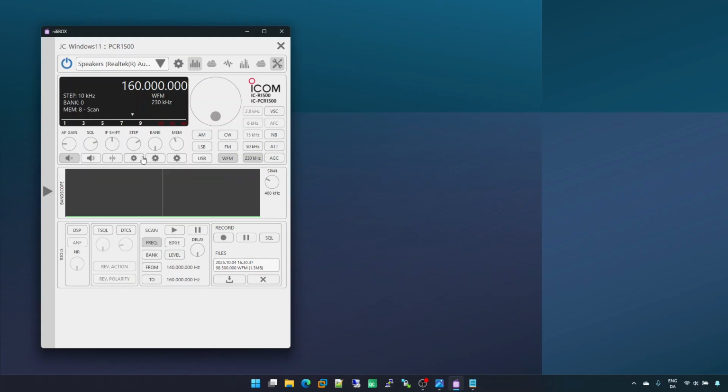Second step is to select what step you are going to use for this scanning, what is the squelch level that you want to use to consider that it has found a certain frequency, and what is the delay. That means what will be the speed, how fast the scan will be done. Now if I press on start, you will see that it is going through this range of frequencies in steps of 10 kHz and it is not finding any because the squelch is not reached.